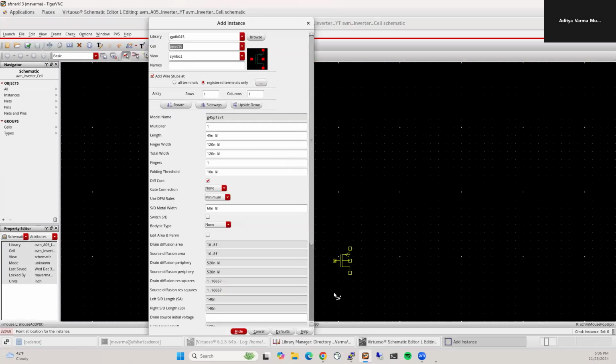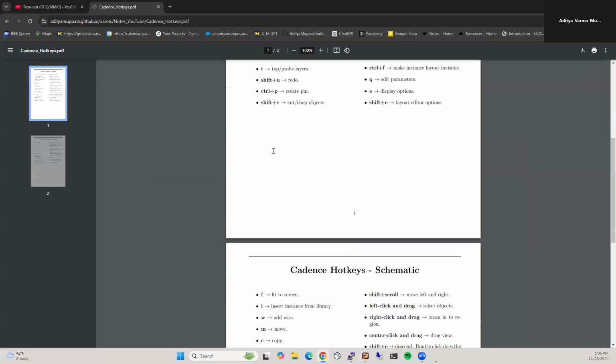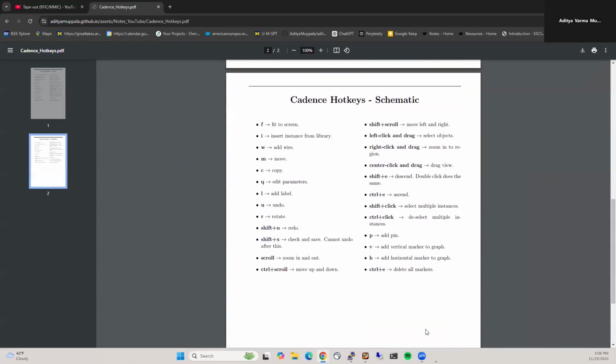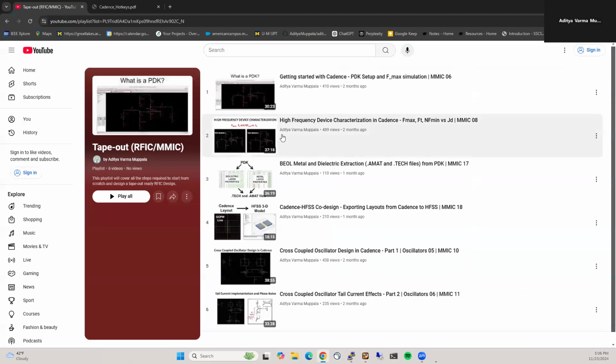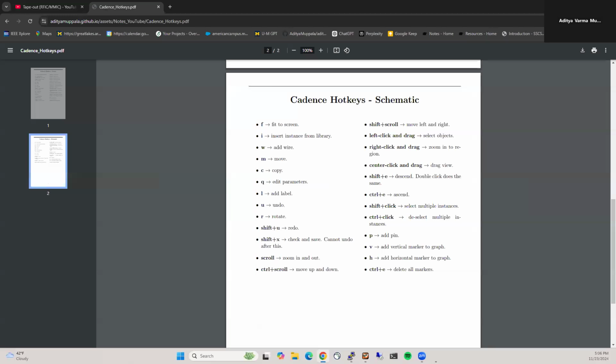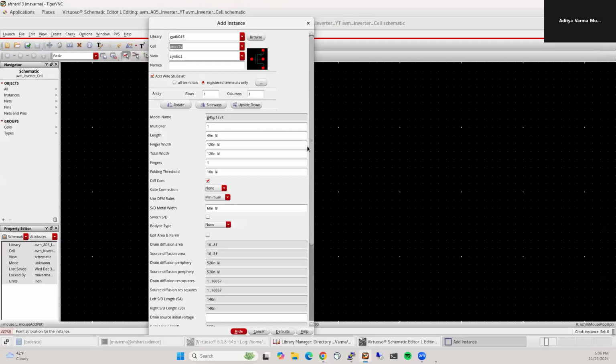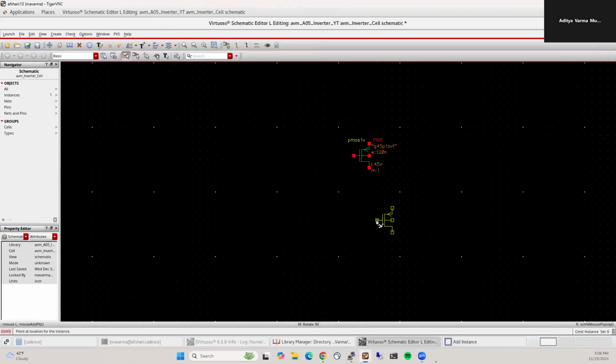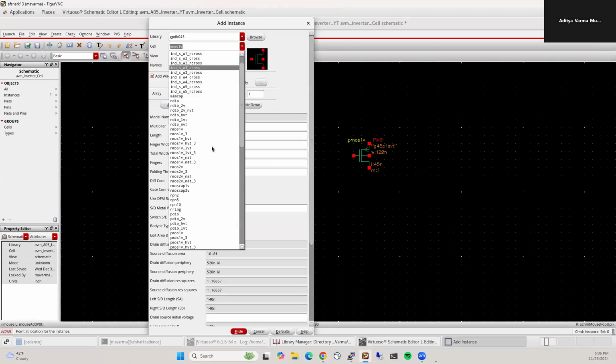If you don't know the shortkeys for schematics, I would recommend going through it here. I think I went through it before already in this video. So if you haven't done that before, maybe watch at least one of these two. Even this one, I think I go through the hotkeys in schematics, so I'm not going to do it again. But essentially, you can hit I and get to instances. So let's set up a PMOS and then an NMOS.